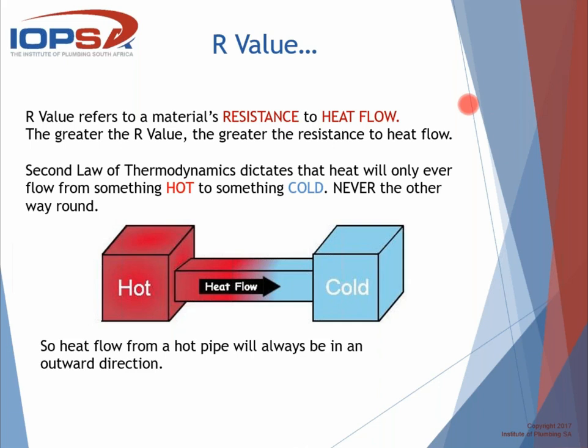That's why it's called the R value. So it refers to how resistant the material is to heat flow. If I put this material in an environment where to the left of it is 20 degrees Celsius and to the right of it is 10 degrees Celsius, how much resistance will it have to prevent the heat flow from the higher temperature side flowing through it towards the lower temperature side? That's what the R refers to.